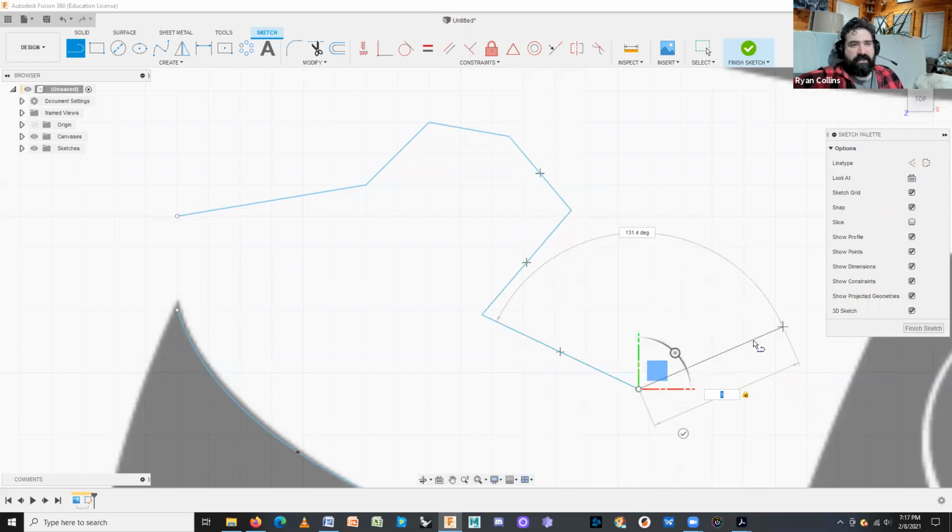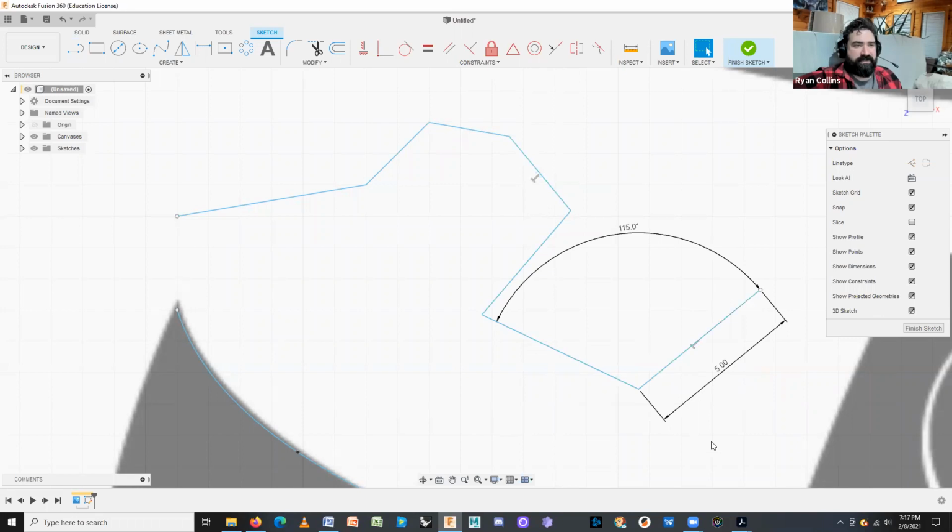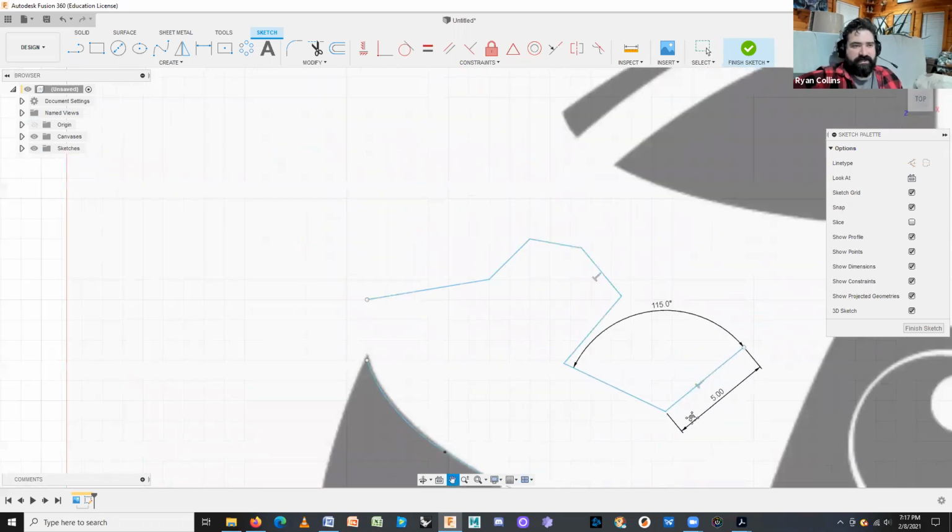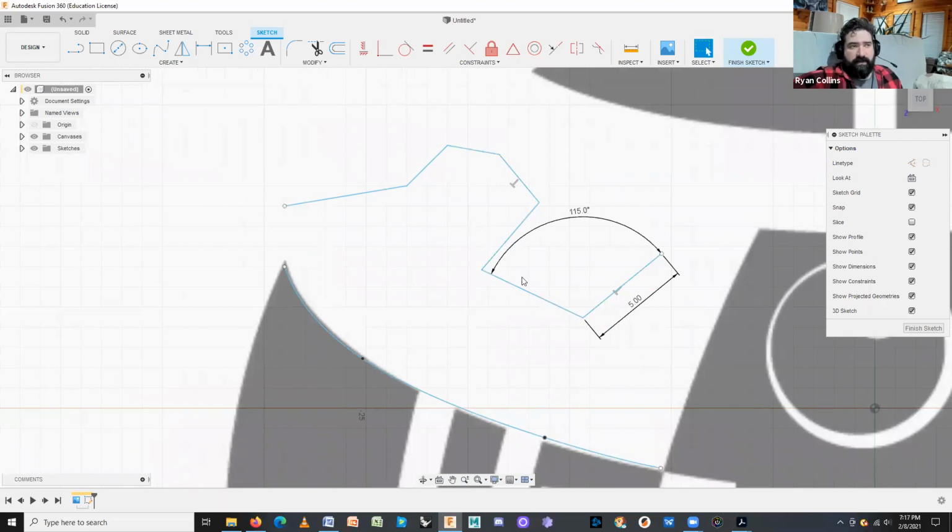Now I can select the arc length based from the previous line. If I want to actually set the angle there, I hit tab and it selects over. Now I can say, I'm going to make that 115 degrees. There we go. Now I can hit enter, and that one line will be different. Since I added actual dimensions, you'll have actual dimensions. Those are super convenient if you're trying to actually draw something specifically. But otherwise, you can freehand stuff with a line tool and the ellipse tool, or sorry, the fit point spline. Those are going to be your main go-tos.